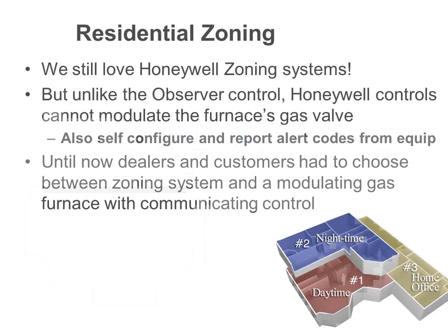So previously in the past, you had to pick when you wanted a modulating gas furnace. Do I want to use zoning, like Honeywell type zoning, or do I want to control the modulating gas burner? You had to pick one or the other. You couldn't do both. Now with the observer zoning, we can do both.